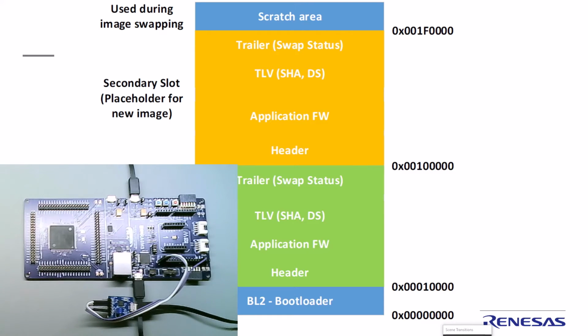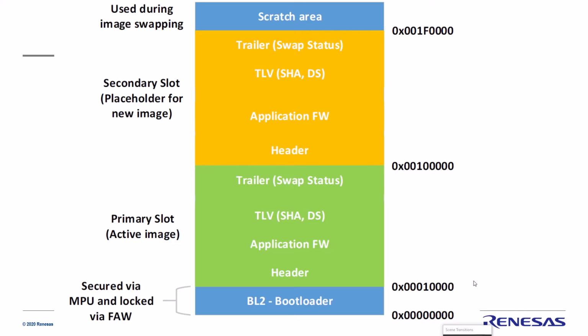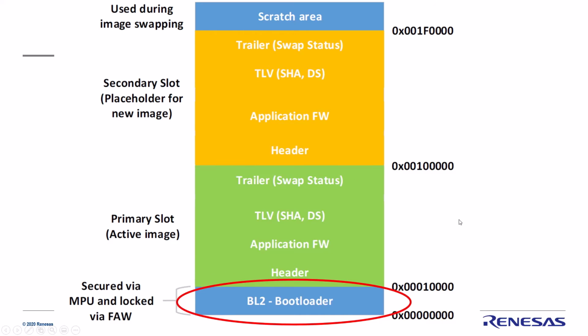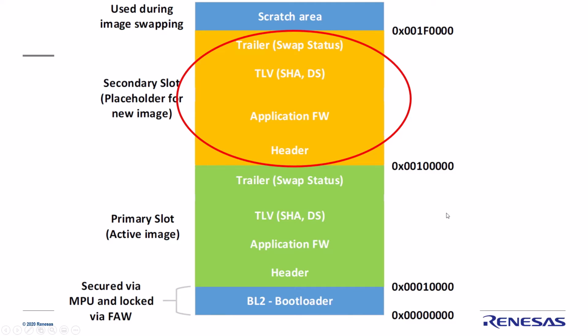What we'll now do is as follows. We'll first develop a simple application to flash 3 LEDs. Subsequently we'll load the bootloader, and then we'll modify the initial application to only flash 2 LEDs, so you can see that it's a different application. And once we boot the device again, the bootloader will validate the secondary slot image first, and then transfer it to the primary slot.